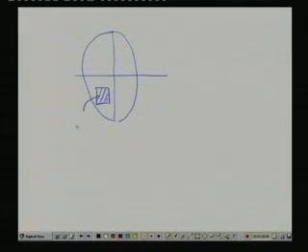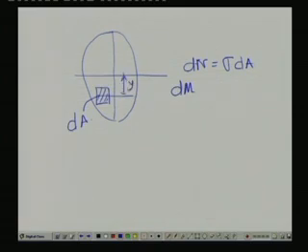Over that one dA, what is the force? We found out the force. Force is dA multiplied by the stress. So, delta F, if we consider a small normal force, is sigma into dA. What is the moment? The amount of moment generated, dM, because this is at a distance y, becomes equal to sigma dA into y.